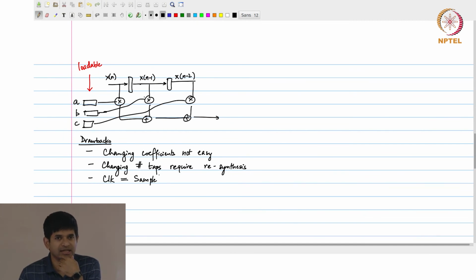It basically means that yes, I am designing a system where even if my sample period that I require is only 1 microsecond or a few milliseconds, I basically have to create, and my clock in principle could operate at, let's say, a few megahertz or even gigahertz. It doesn't matter as far as I am concerned. I still need to just operate that system at a slower rate, right? My registers that are capable of switching at hundreds of megahertz are going to be kept slowly switching at whatever rate is actually required by this clock, okay. So even the fact that my hardware may be capable of operating much faster than I need, I can't really make use of that, okay.